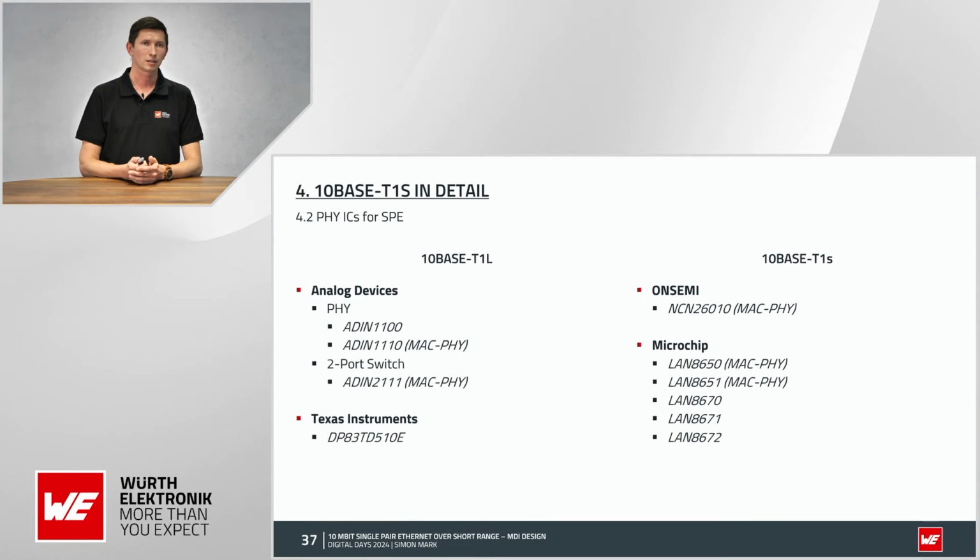My last slide is about the PHYs. A small summary: on the left side is the 10BASE-T1L. We have from Analog Devices several ICs for the 10BASE-T1L, also from Texas Instruments, and for the 10BASE-T1S from onsemi and Microchip.